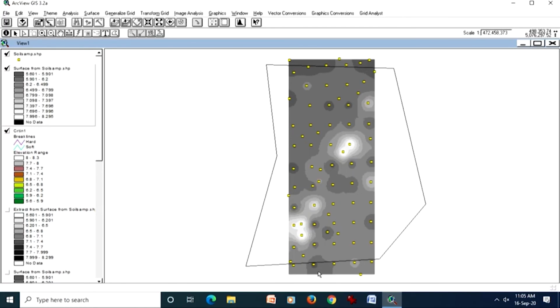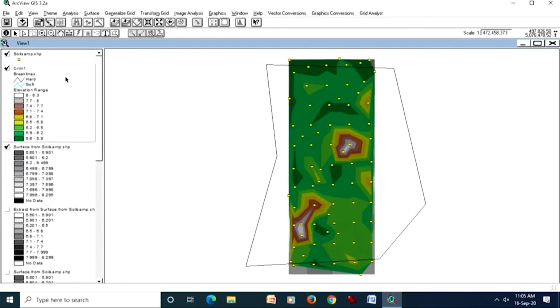And if you compare this with the TIN, then TIN will also go, but because theoretically or practically the raster has to be stored either in rectangular or grid form, because it is a two-dimensional matrix and number of rows and columns need not be the same. So two shapes are only possible, rectangular or square. But in case of TIN, this condition is not there.